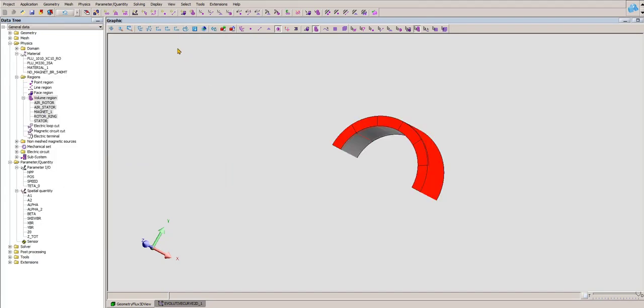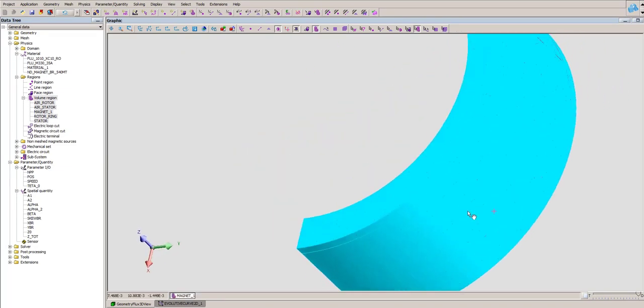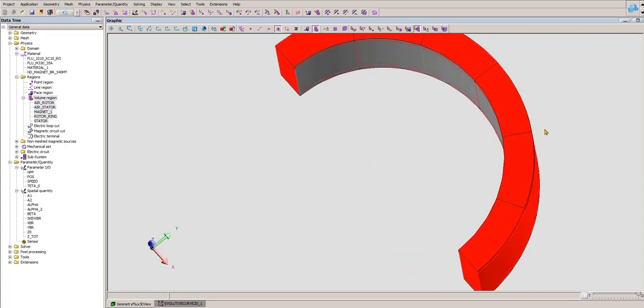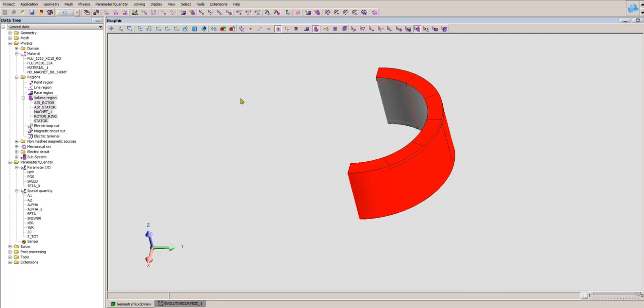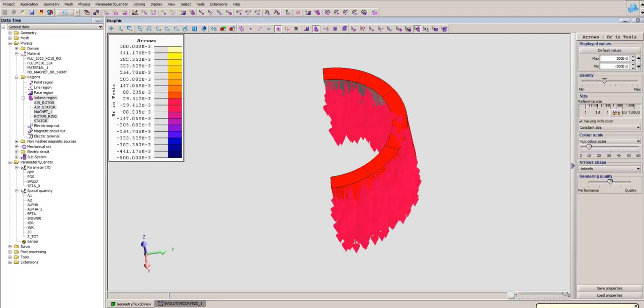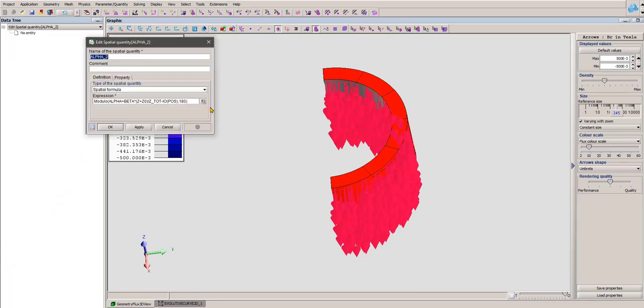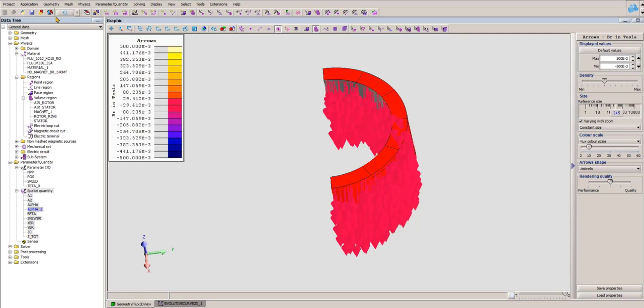So once again, the interest here is that you can use extrusive mesh and a linked mesh on the portions, and this means that you will have a really very good mesh adapted for cogging torque computation. Then you can go and display the rows. As you can see here, they are all in red. Why? Because I am using rotor position here, and if the project is not solved, Flux does not know this initial position. So I will just replace it here by 0 in order to show you the results.